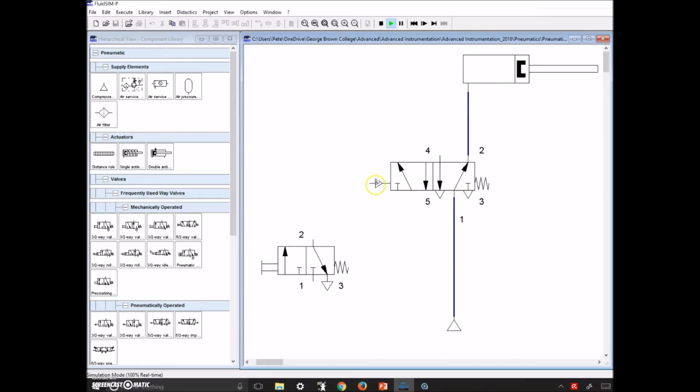So now we need a signal coming in here in order to make it retract. So we'll have the 3-2 bring that signal in. Let's stop this for 2 seconds. We're going to bring the air from the 3-2. Looks good. And then we just need to bring a source of air. Remember to hover over this and then drop it in. It'll connect it up, and that'll give us our source of air for that 3-2. Excellent. Okay, we'll hit play now.